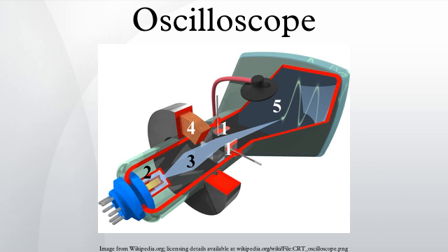Another use is to check newly designed circuitry. Very often a newly designed circuit will misbehave because of design errors, bad voltage levels, electrical noise, etc. Digital electronics usually operate from a clock, so a dual trace scope which shows both the clock signal and a test signal dependent upon the clock is useful.